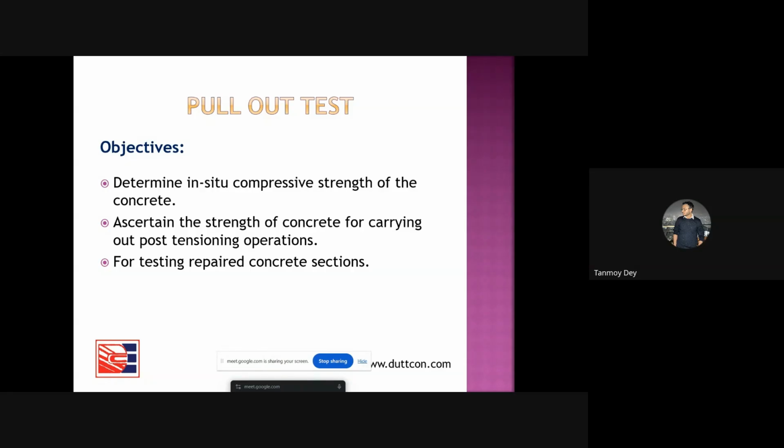Theoretically, it is true; we can measure through the rebar locator. I'm telling you why I'm telling you about the rebar locator here. Through the rebar locator, we can understand the presence of rebar, how much rebar is there, what is the spacing, what is the diameter. The principle is based on magnetic lines of force.